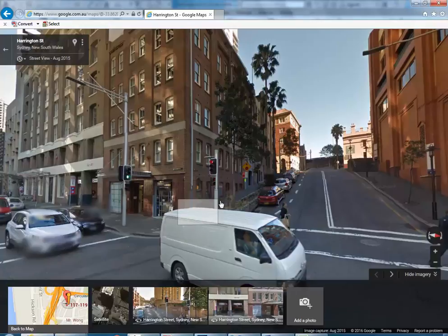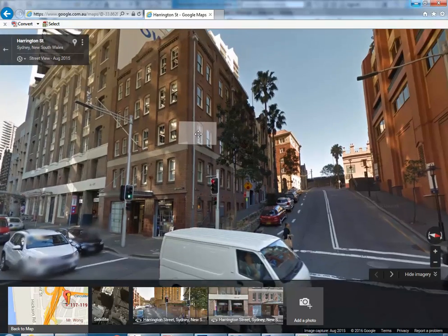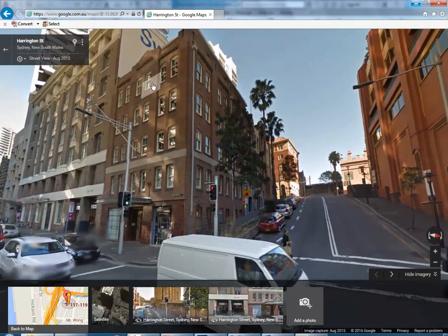For now, though, I'm going to pretend that the road isn't there and just create the ground floor going all the way down to the height at the lowest point. So I'll make my walls from that point, and we'll take them all the way through. Luckily, this building is pretty much straight up and down.